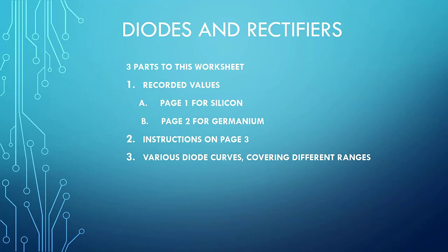We can see on the left-hand side, the voltages stay pretty much the same on the bottom, but our range of current is different. On page 4, it's 0 through 12 milliamps. On page 5, it's 0 through 120. Pick the right sheet. If you're under 12, pick the 12 scale. If you're over 12, you're going to have to pick the 120 scale.